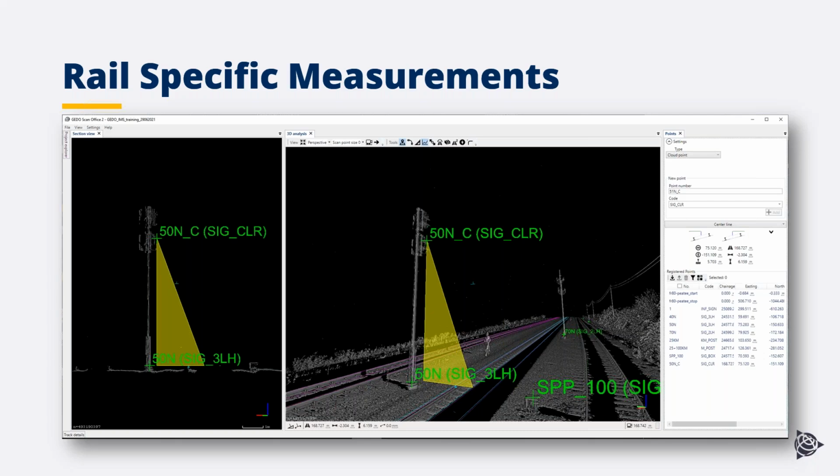Both are measured at the running edge position for the horizontal part, and top of the rail for the vertical part as well. This data is accompanied by information about the track cant, super elevation, and the gauge. So this is nothing very simple. We might think this is just two lines. No, this is not two lines. This is quite complex data about the rail. And what's important is that it matches the track measurement regulation.